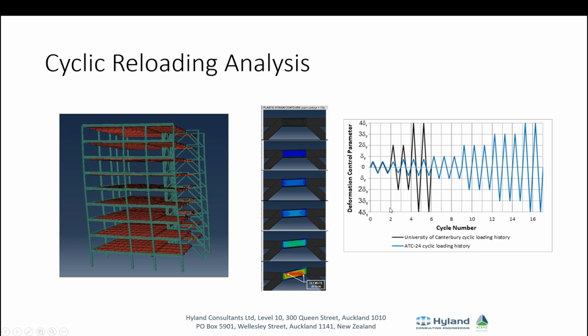We also knew from the location of the building and the way buildings with similar natural frequencies had performed in the earthquake that there were a couple of strong cyclic displacements, perhaps 4 times the first one, and so we used this to come up with a bit of a synthetic cyclic reloading analysis, and tried to benchmark that against the actual deformations we measured on site.